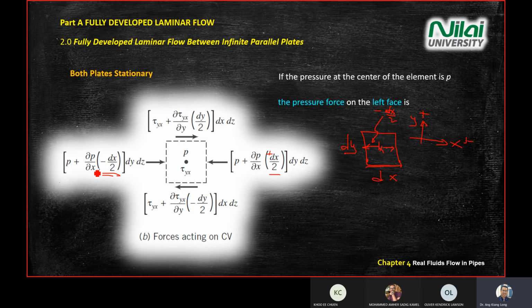All right, now why you get this del P over del X? It's the differential of pressure, the pressure difference on this side. Because at the center of the cube, if you move to the left, there's a change of pressure, which we write as del P del X. There's a change of pressure in X direction. This is the Taylor series definition.